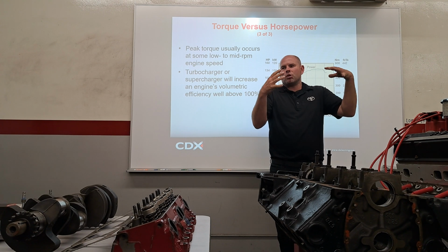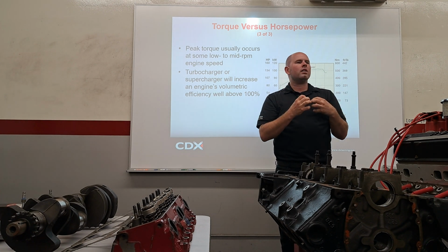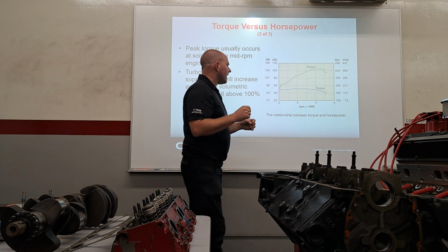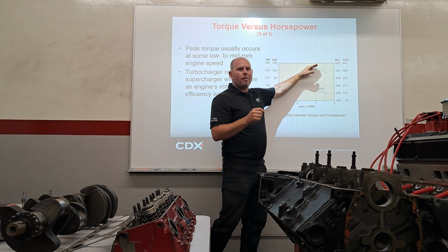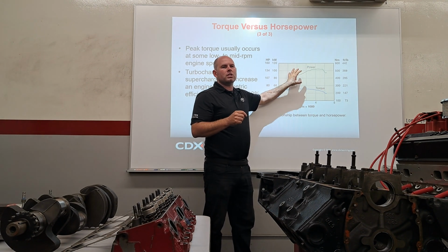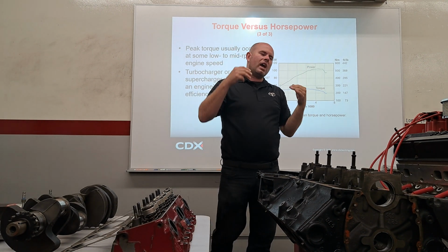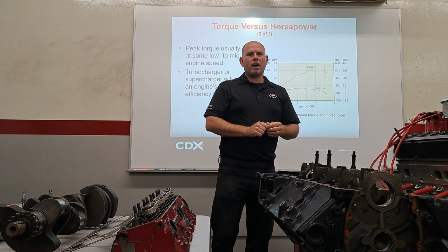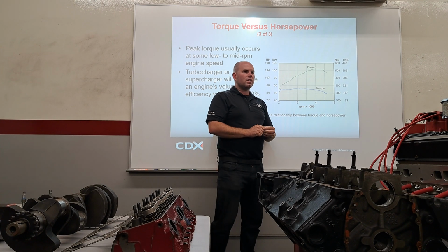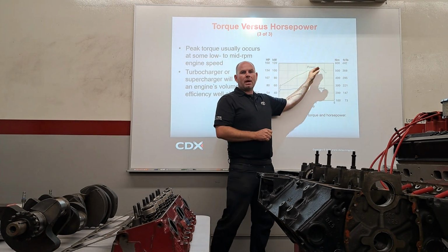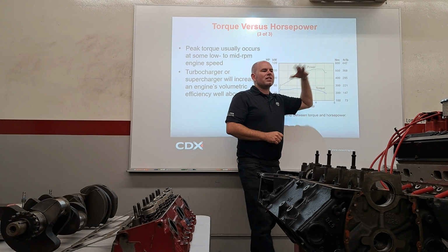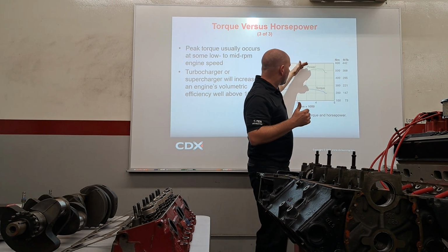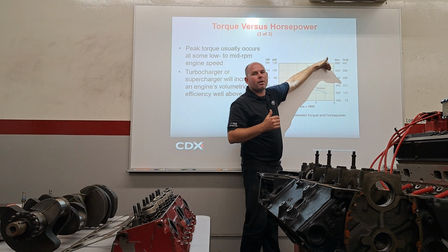So do you think we were able to really fill the cylinder at the high RPMs? That's part of the reason why the horsepower does go up, because we're getting more RPMs, but it's all about how well we can move that air, and that's a term that's actually going to be brought up called volumetric efficiency. So if you had 100% volumetric efficiency, you'd have that engine making as much power as it possibly could. But if it starts to get into higher RPMs and it can't pull the air in fast enough, look what happens. It starts to tail, it starts to drop off.